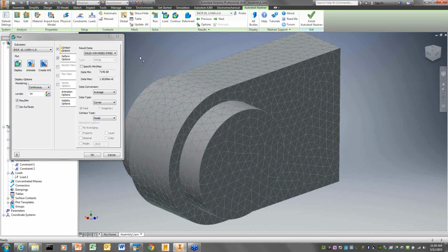So, I mean, if it's not generating any information there may not be any contact occurring. Yeah, it may be zero. Yes, because Nastran has a terrible habit of if you get zero results, it just doesn't create them. So you run a model without any loads on it, and it runs, but it doesn't generate any results. You're like, why don't I have any results? And, oh, there's no load. So I've had that happen too many times to count. And it may just be that there's no contact occurring, so it's all zero. So you're not getting that vector because there is no contact.